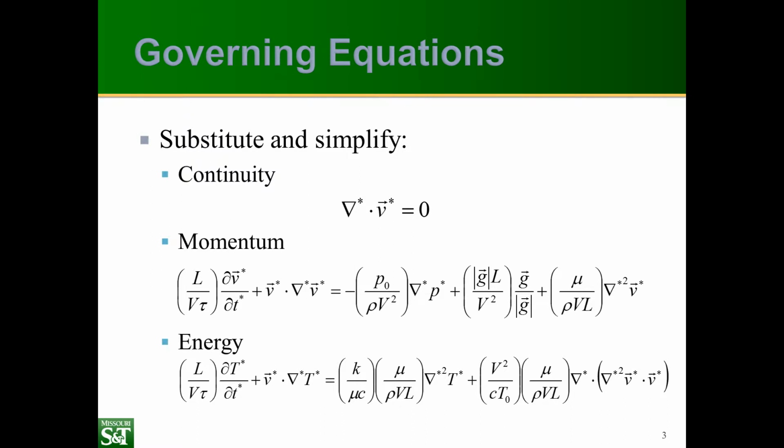However, momentum does. We have a time scale. Over here we have a time scale. We also have a scale for the pressure. Again, if we used 1/2 rho v squared as our scale parameter, then P0 is 1/2 rho v squared, and we can get rid of this ratio. We also have a gravity scale, which scales gravity or gravitational forces to momentum, and we have a viscosity scale, a scale for the viscous forces.